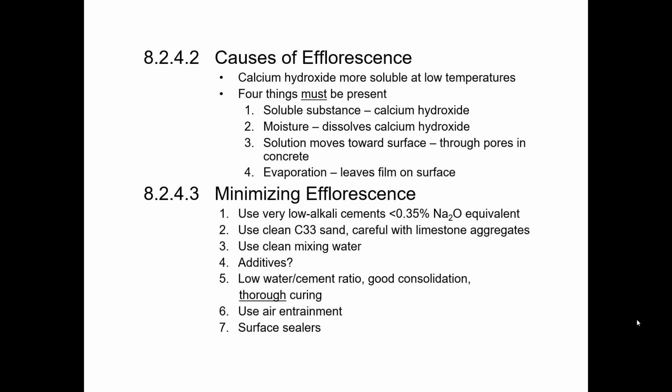We've got additives on here. I'm not aware of any additives that have been shown to be consistently successful in eliminating efflorescence. I'm sure there's things out there that you can add to the mix that will maybe slow it down a little bit, but if you could come up with a good one of those, you could most likely make a lot of money.